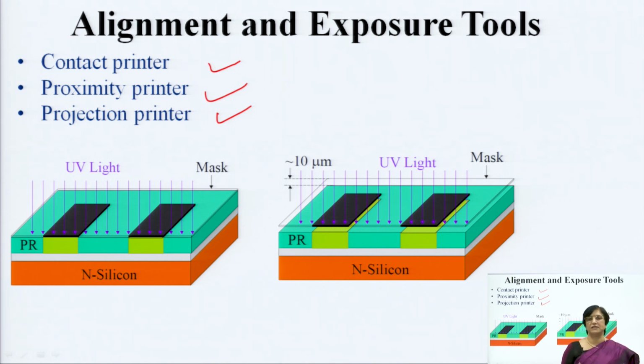What are the masks? A mask is basically a transparent plate, either of glass or some other material with fine thickness, and to have opaqueness, you either carry out emulsion coating onto it, or for precision you coat with chrome.